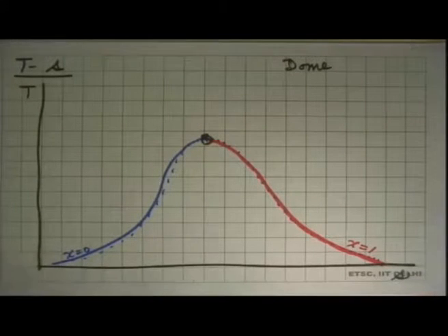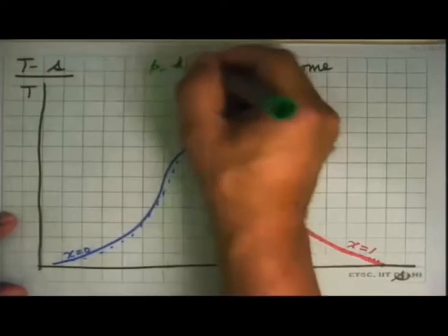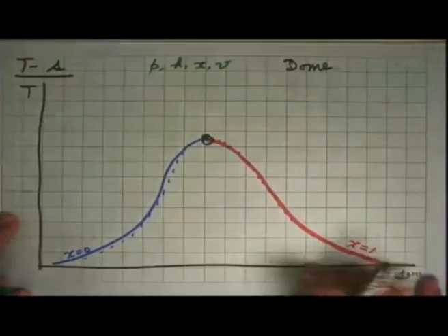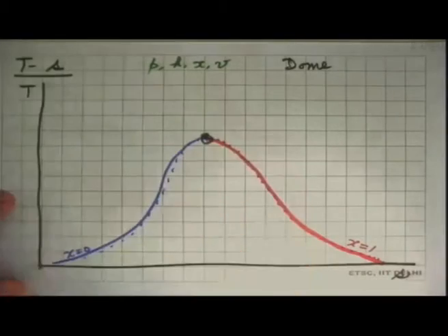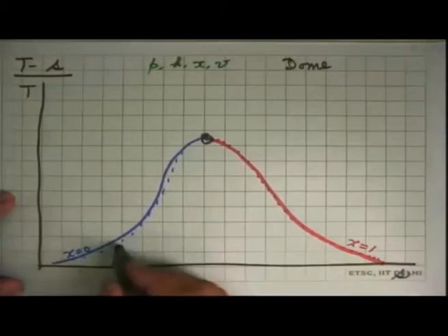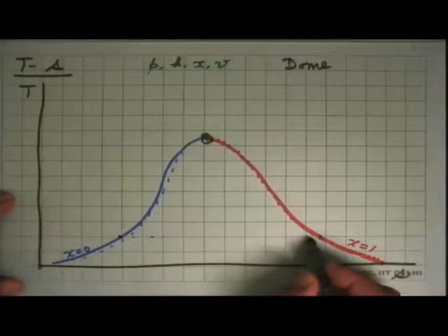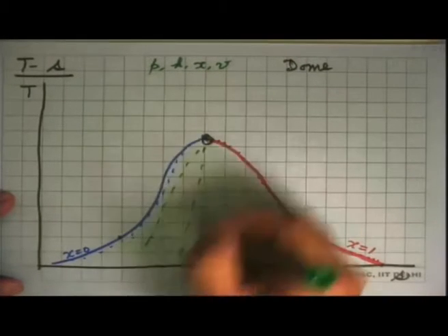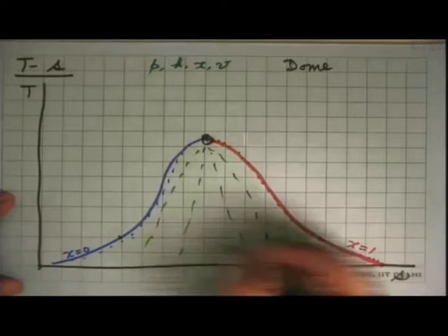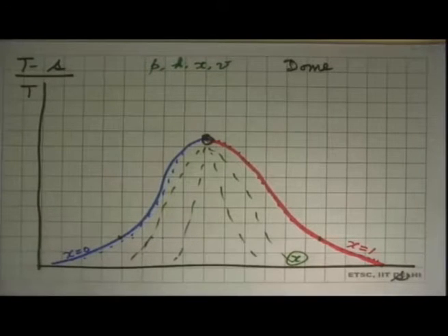And what happens here is we can now ask for what constant pressure lines. We can ask for constant enthalpy lines, constant dryness fraction lines, and constant specific volume lines. Okay, so the easiest one is x, and this will follow exactly the same style as we had earlier. At any given temperature, x equal to 0 is here, x equal to 1 is here, it is increasing monotonously here. Same with every pressure. So constant dryness fraction lines will all look like that. So these are constant dryness fraction, and they are always inside the dome.